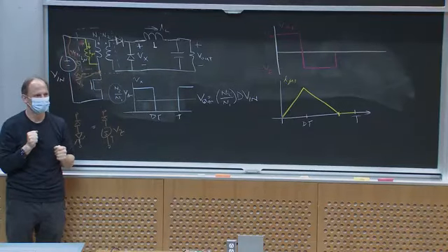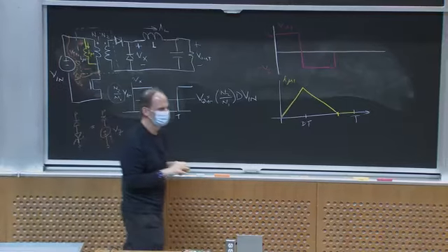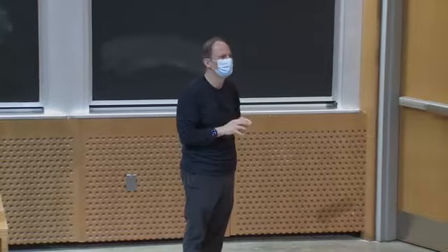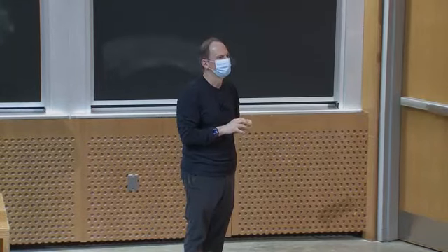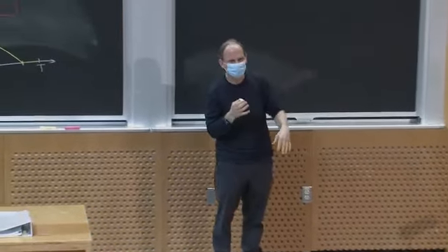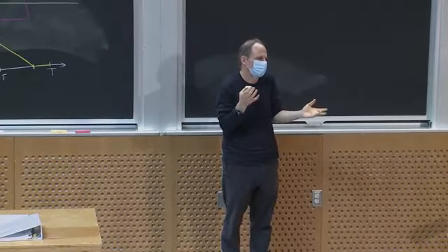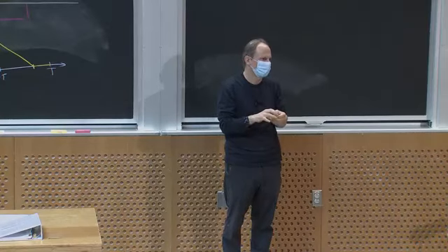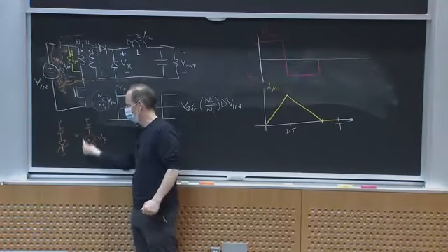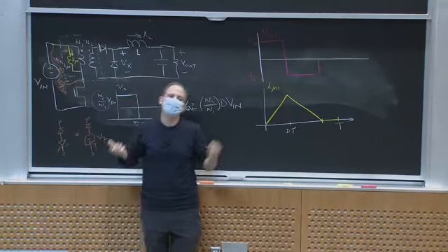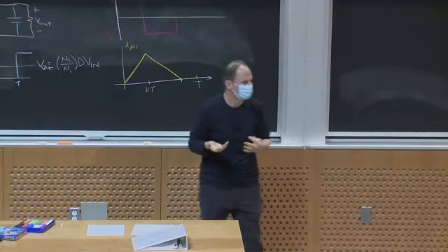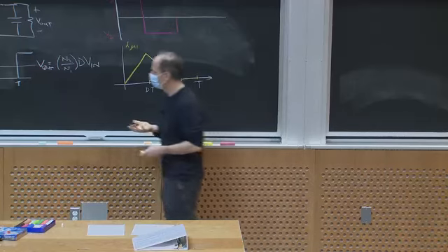Any questions about that? Why do you choose to use Zener diodes and not like one freewheeling diode? Because think about a freewheeling diode: it has a forward drop that's like 0.7 and a reverse drop, and you don't want to try to put a current through a diode backwards. The Zener is designed to sort of hold a constant voltage when it's breaking down in reverse. And I might not use a Zener, I might use some other element that can absorb energy in the reverse direction.